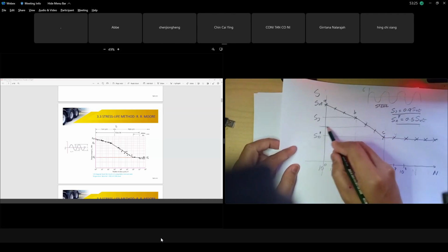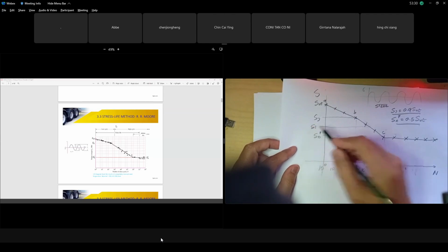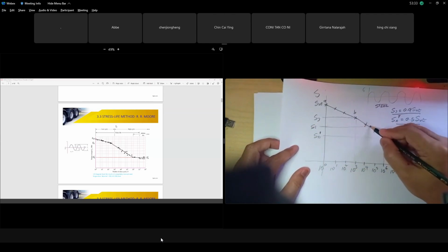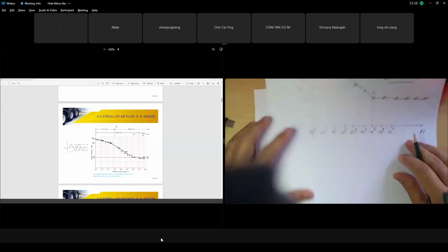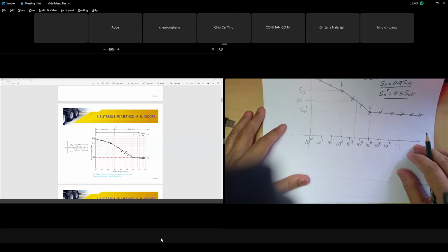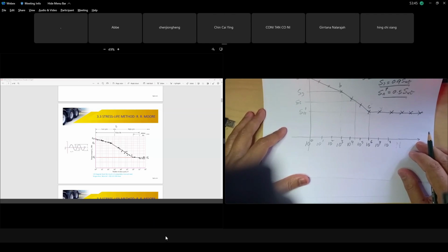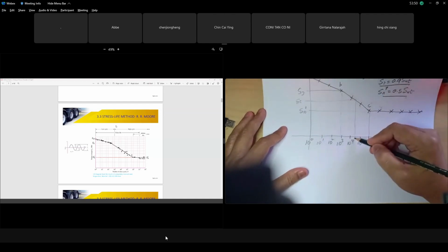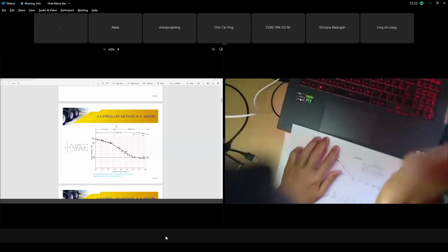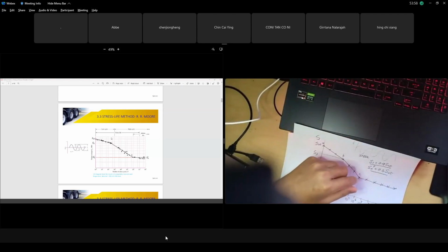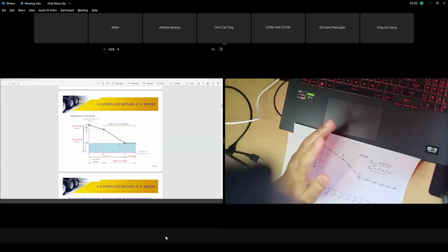You can bring your line. Okay, this is your case's stress, your fatigue stress, SF. You can bring your graph here, and you can bring it here, and you can estimate at what cycle it will fail. Is that clear, class? Is what I am saying clear? Class, are you with me or not? Okay, then you can see at what cycle it will fail. All right. I hope you understand what I'm talking about. If you look on the slide, that's why I'm talking now about SN.